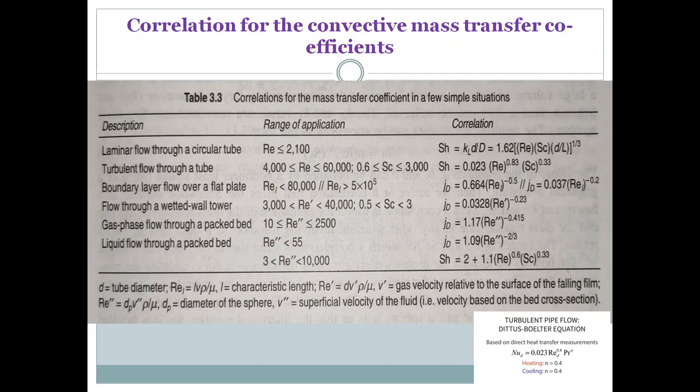That's why I am telling you to be smart enough to convert one mass transfer coefficient to another. When you first calculate the mass transfer coefficient based on a correlation, it is not in your hand; you get whatever the correlation gives. But what you need in a problem may differ, so you have to convert, and we understand how to convert. So this is all about our mass transfer coefficient and how we calculate it.